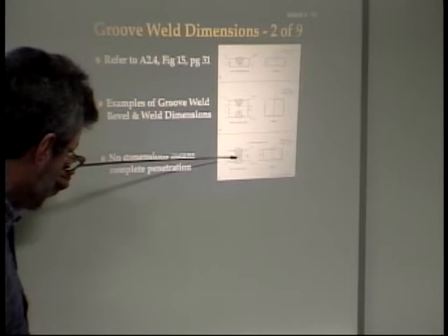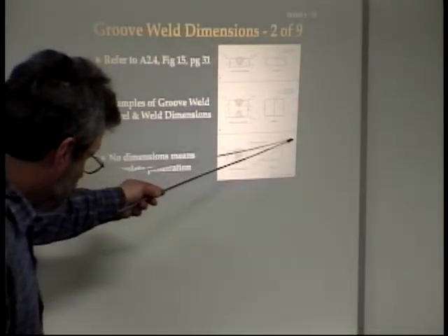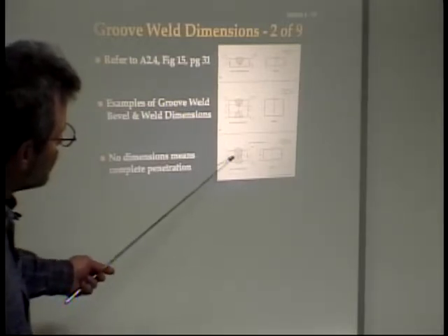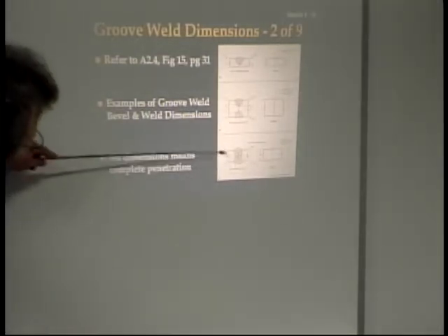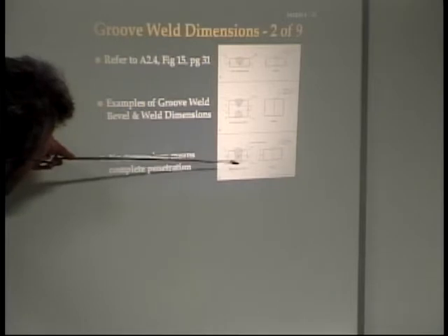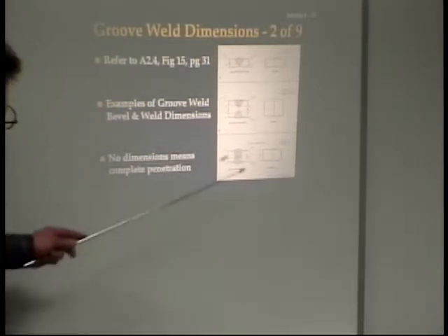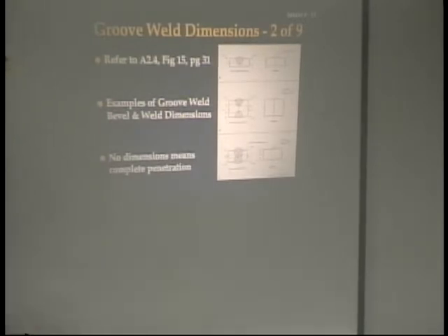And typically they would also put in here, in the welding symbol, a tail that would say, well, let's do some back gouging or back grinding in order to achieve that. You can also look at the drawing and tell that this weld was put in first and then this weld was put in second. So the upper one would be a back weld, or it would have been applied secondarily.